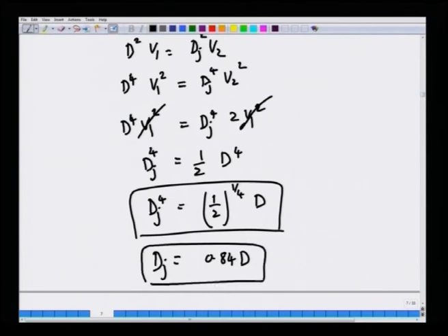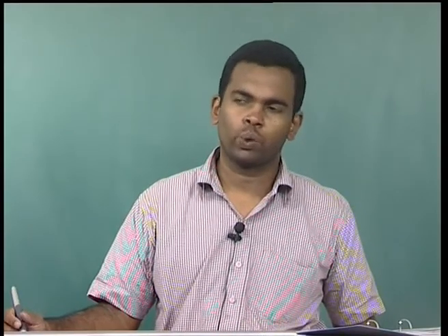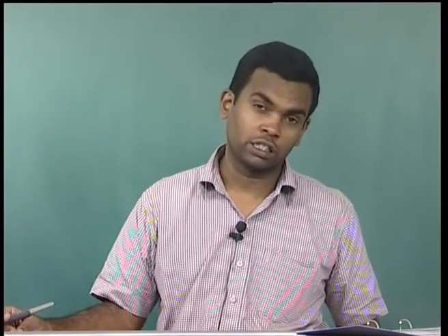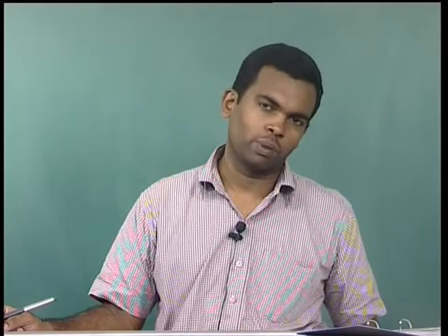This is the result that we get while using the integral energy balance between points 1 and 2, where point 1 is just exiting the tube, and the velocity profile is parabolic while the pressure is assumed to be atmospheric. Point 2 is sufficiently downstream in the jet, where the jet velocity is uniform and the jet pressure is atmospheric.